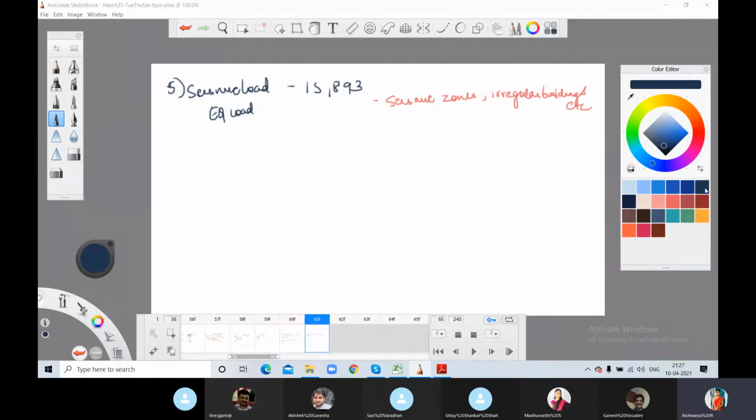The sixth one is special loads. Special load is IS 875 part 5. Special loads are nothing but accidental loads, or when there's an explosion. I'll write it down here, accidental loads. Which doesn't fall under any other category, when there is a sudden influence of some other load, which is not common, mainly due to, like I said, explosions.